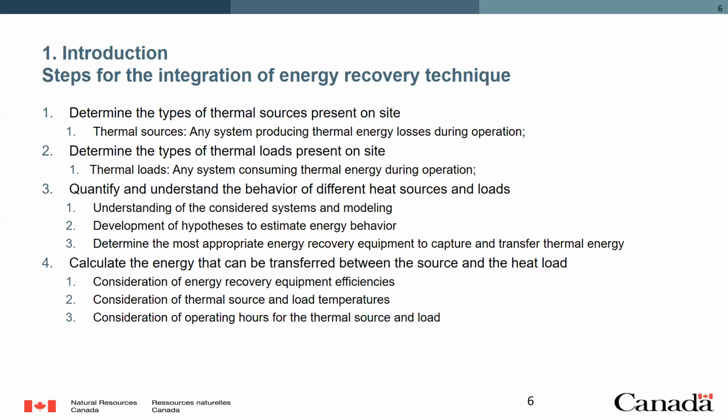So what are the steps for integration, the energy recovery? First, you need to identify what are your sources. Then you need to identify what are your loads. Then you need to quantify what can go from the source to the loads. And the last step is to look at when and how can you do that.